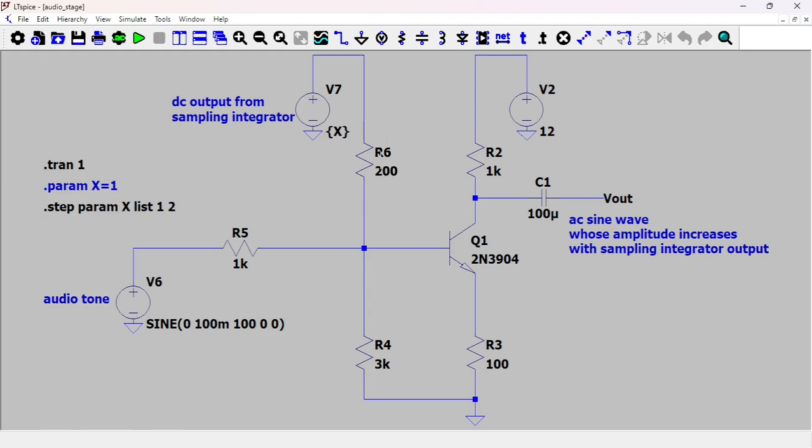Usually, as I said before, this resistor is connected to the battery voltage here, and you don't have this part. The role of the voltage divider bias is to set the quiescent base voltage in a way that's completely independent of the transistor. You cannot rely on the transistor and that 0.7 volt differential to set up your bias voltage at the base, because otherwise it's going to be too dependent on the transistor you use. That's why you use this voltage divider bias.